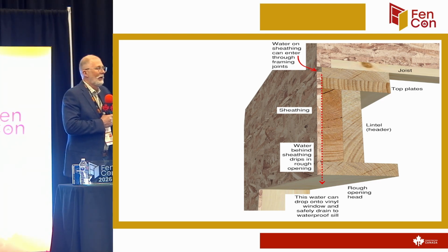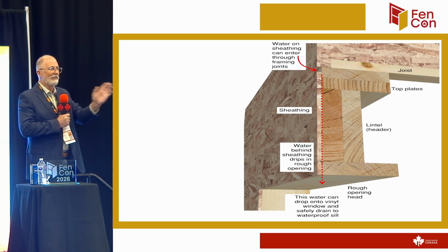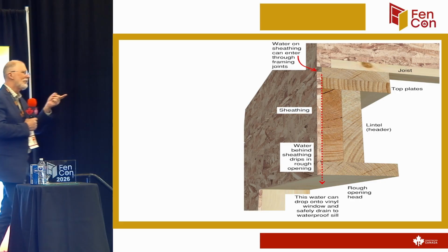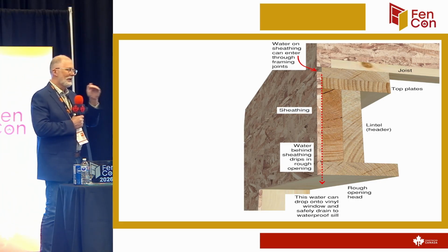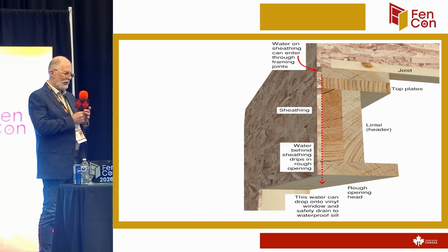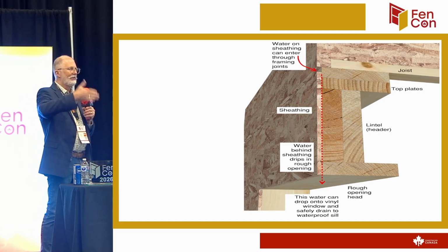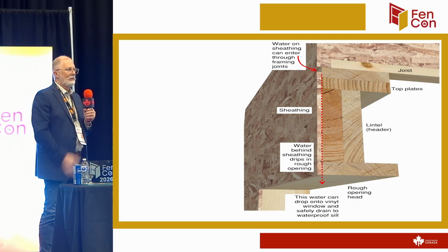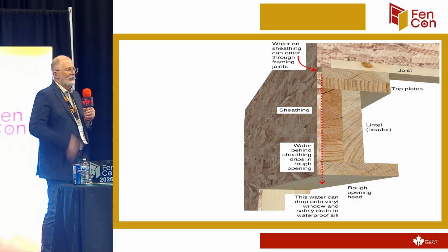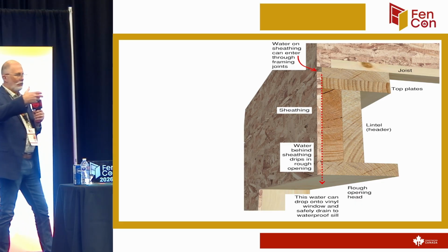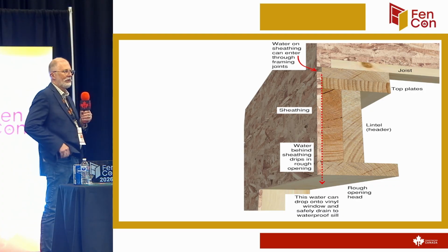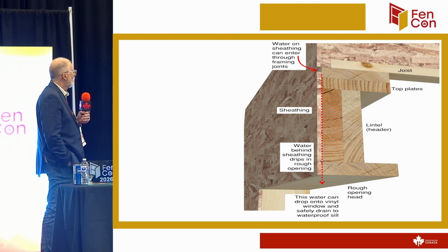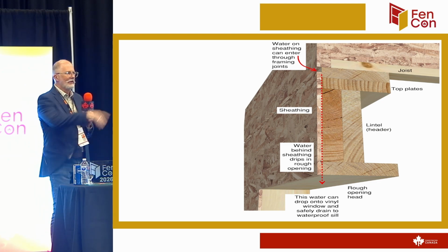So you're absolutely right. If you're concerned, I would just air seal the whole thing, do it at the face. Depending on your jamb extension, if you're buying windows with a built-in jamb extension and you air seal that jamb extension when you install it, put the air tightness at the face where it meets the casing, you've covered it all. As long as the material that's in there can support whatever moisture gets in and drains it out, Bob's your uncle. Does that make sense? Did that answer your question? Yep, go ahead.